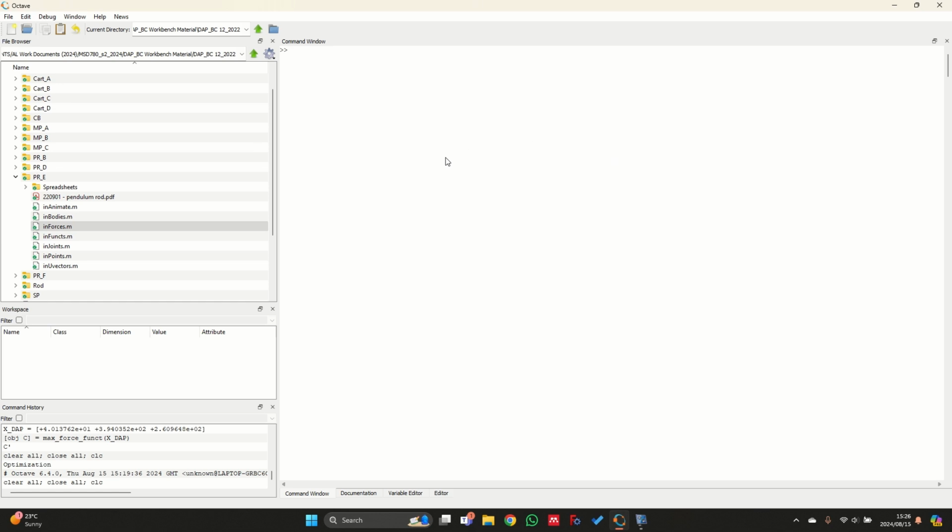Now that we've considered the forward dynamic analysis and the inverse dynamic analysis separately, we can now go and combine the two as well. And the workbench is able to handle that as well. We'll see in a moment that when we specify some sort of a rotation driver, the system will actually apply a braking torque when it calculates the Lagrange multipliers.